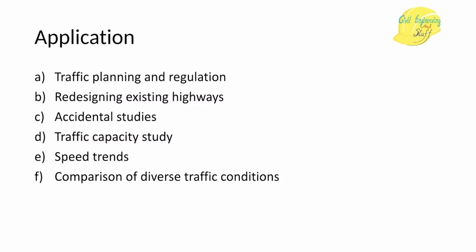By speed study, we also find out the speed trend, that is, what is the speed bracket that has been maintained by most of the vehicles, and what are the diverse traffic conditions in the road section. So what are the vehicles that are moving in that road section, and what is the average speed that has been maintained by those vehicles.